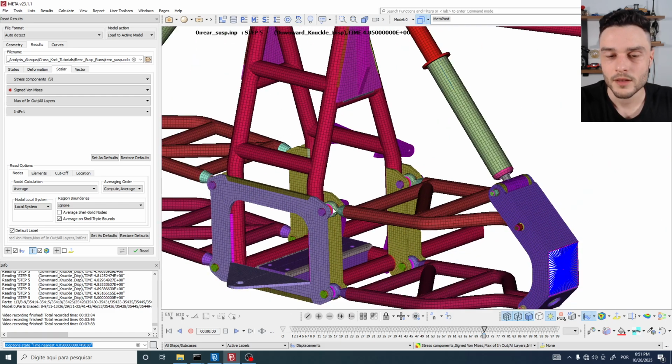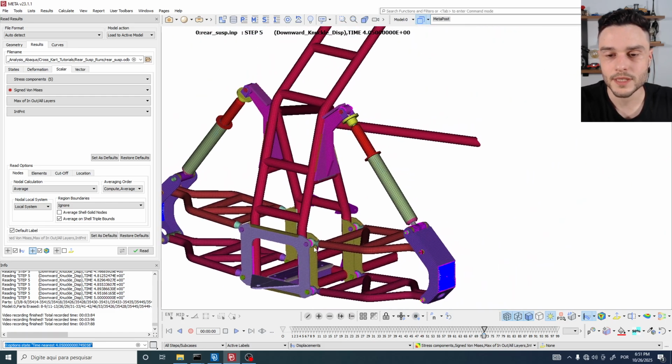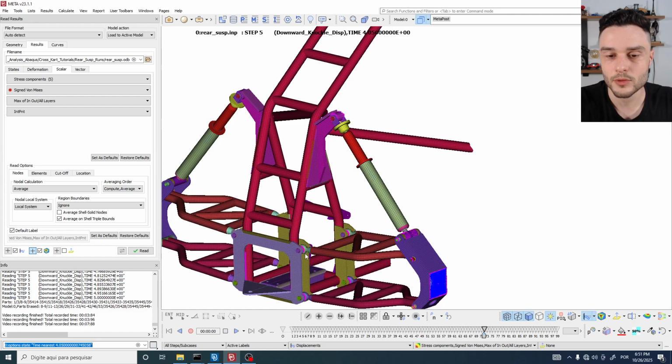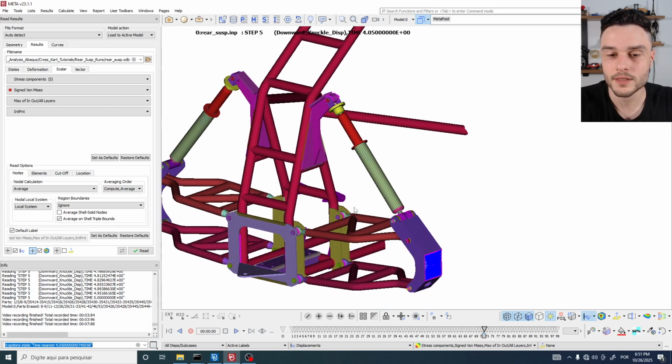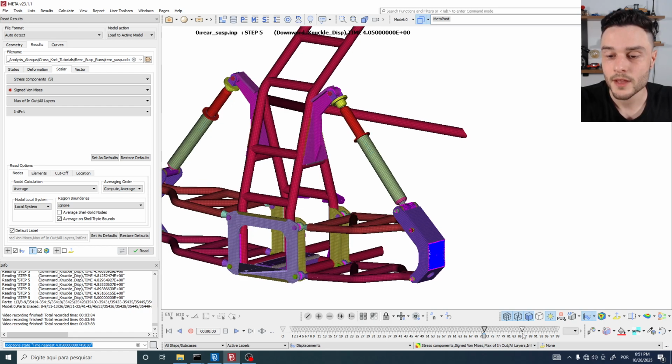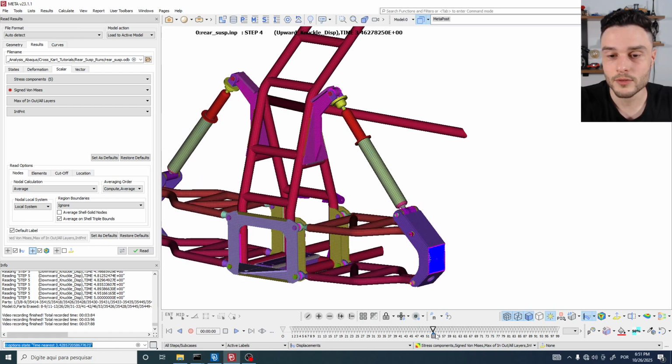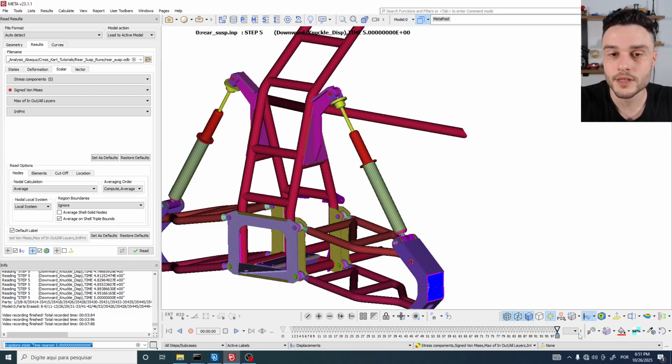We have a little plasticity occurring, which is acceptable in regions of contact because they are compressive in nature. We have also frictional contact, which is another kind of nonlinearity. So anyways, we have all kinds of nonlinearities occurring here. So this is a pretty good exercise to practice about nonlinearities.